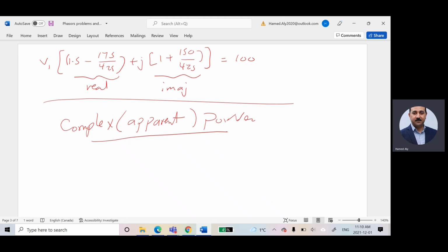This is what I'm seeing. I have a heater, and I'm taking heat from that heater. This is coming from the active power. I have a lamp. There is something happening inside it, but at the end, I'm seeing the light. This is the active power that I'm taking. But what about the reactive? It is the magnetic energy inside the machine itself. I'm not taking it, but at the same time, without it, I couldn't have the active power. That's why we are defining the power by two different components.